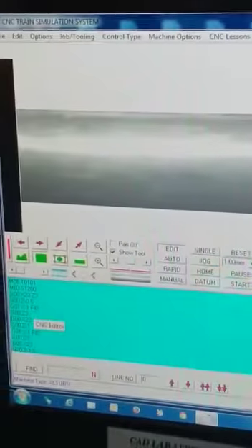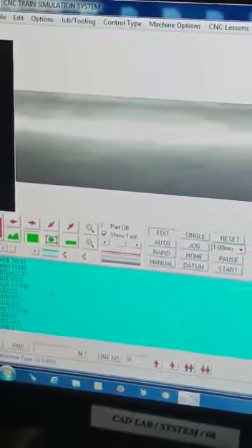So you have to reduce 1 mm. From this 22, you have to reduce 1 mm. Feed, how much feed you are giving, that is 45. F is your feed rate. S is your spindle speed and F is your feed rate.